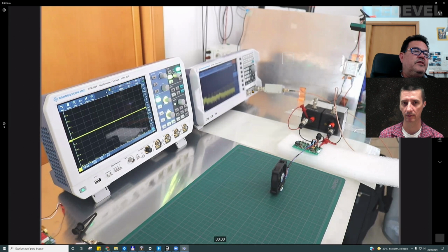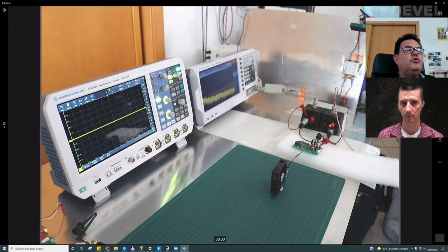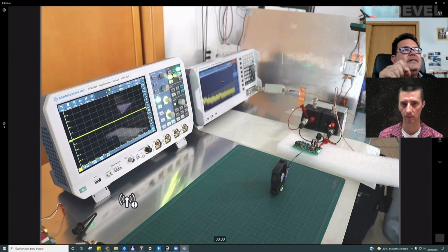But it is very important to know the frequency response of this element, or for example the losses of the cable in the frequency range, because then you need to introduce in the spectrum analyzer or the EMI receiver what we call the correction factors. The correction factors mean the instrument automatically corrects the real amplitude of the signal you are measuring. If not, for example with a 3 dB attenuation, the signal on the screen looks lower than it really is, because it is being attenuated. So it's very important to know this.